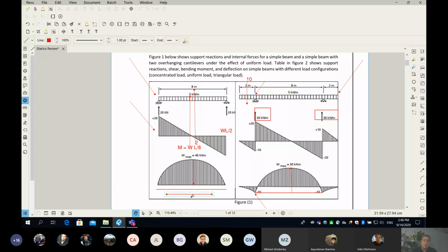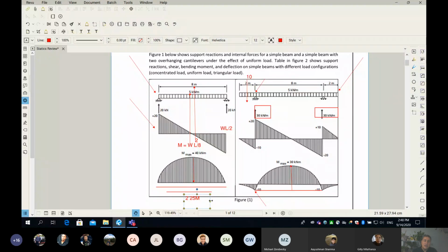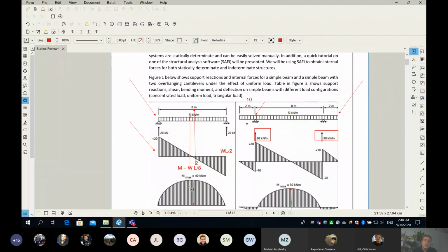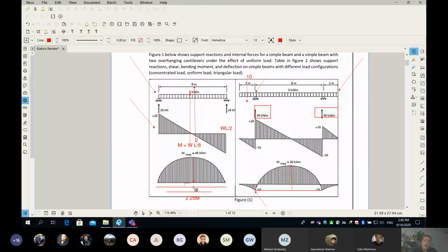So this one here will be, for example, 2 rebar, and those will not really go all the way to the support. And then I have 3 at the supports. Please watch this. The section in the middle will have 5 because your maximum bending moment needs 5.